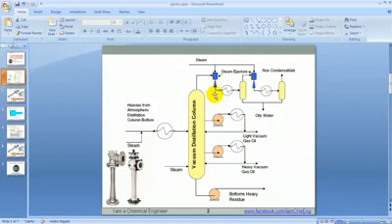In the atmospheric tower, crude is heated up to a specific temperature depending on the crude type and its origin. At that temperature, you can obtain distillates, middle distillates, and residue. Distillates come from the top of the tower, middle distillates like light vacuum gas oil or gasoline, and the residue from the bottom. On most occasions that is not satisfying enough for a refinery. They need more light products. Unfortunately, heating cannot do the trick.